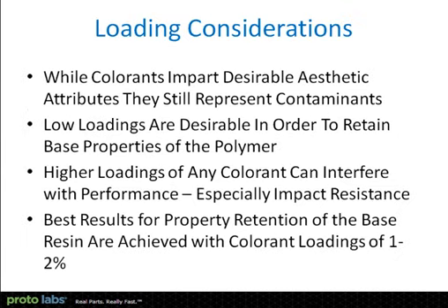So loading considerations are key. While colorants impart desirable appearance, they still represent contaminants. And so low loadings are desirable. We want to try and keep the level of colorant to a minimum in order to achieve the appearance we want to see. Anytime we go to higher loadings of any colorant, we run the risk of interfering with performance. And usually the first property to run into problems is that of impact resistance.